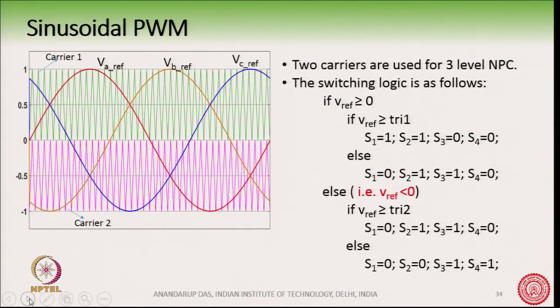Now, in the sinusoidal PWM strategy for a 3 level NPC, we have 3 sets of sinusoidal modulating waveforms and carriers. Both level shift PWM and phase shift PWM can be used in the 3 level NPC, since it is a multi level converter.